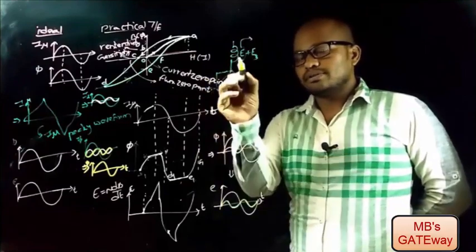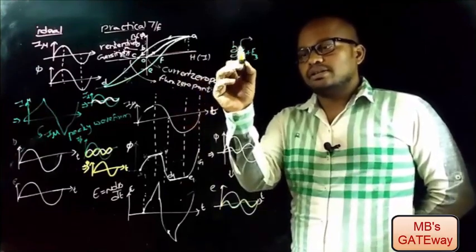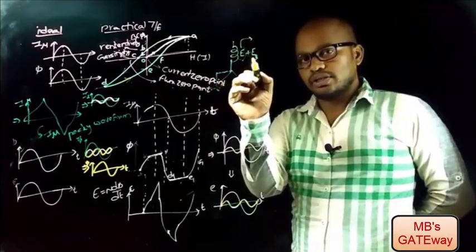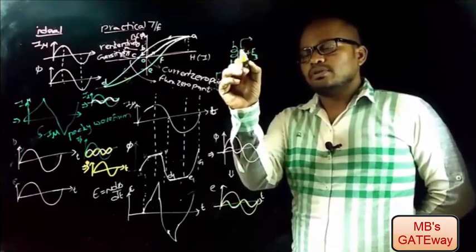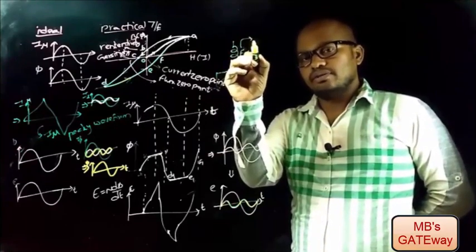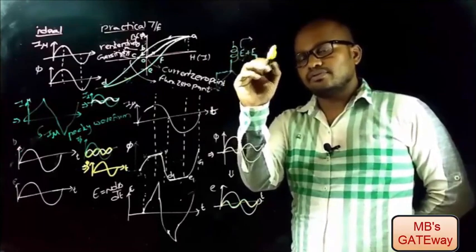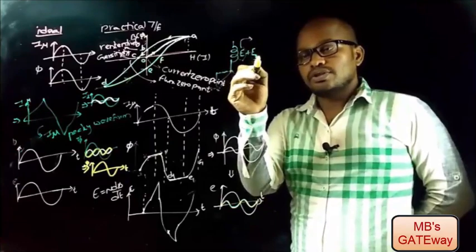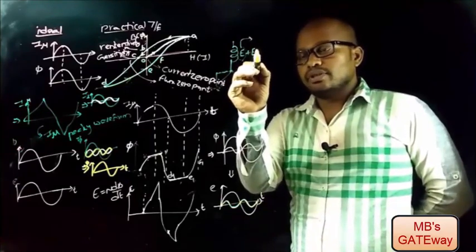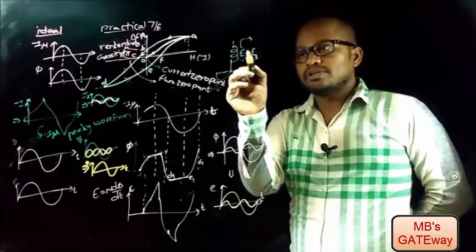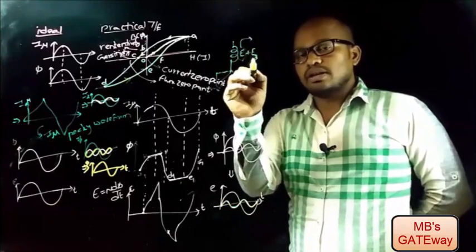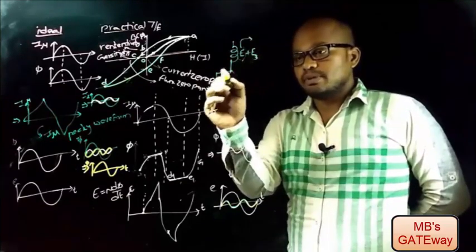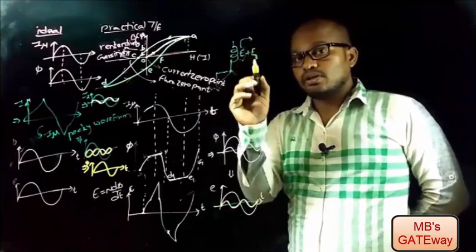And if you remember the concept discussed previously, in an alternator the induced EMF has a fundamental EMF and a third order harmonic EMF, and when the load is connected, because of this fundamental EMF there is current I flowing in the lines and phases of the load, but as E3 is cophasal, that is a triplen harmonic which doesn't satisfy the fundamental property, there is no path for the triplen harmonics from phase to phase or line to line, and these triplen harmonics are reduced by providing a neutral connection, that is by providing a path we are reducing the third order harmonics.